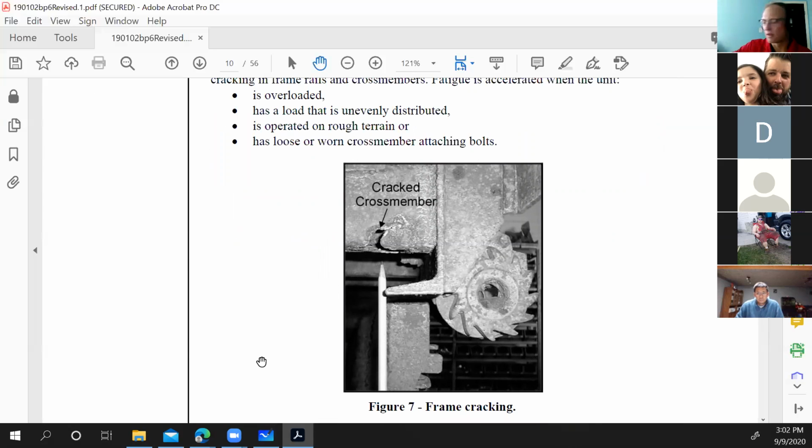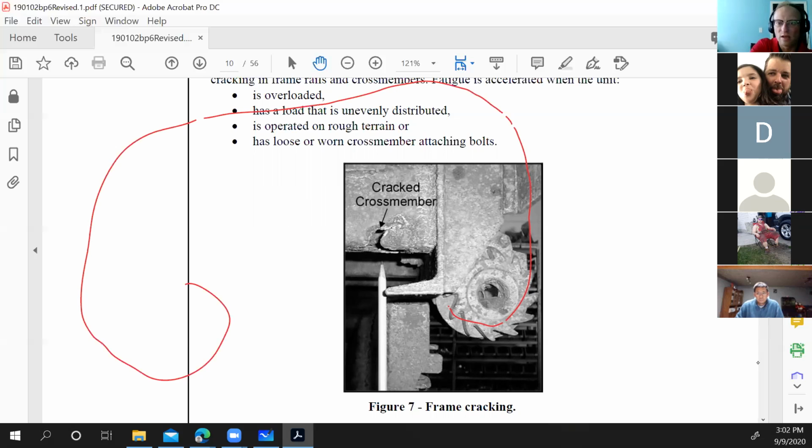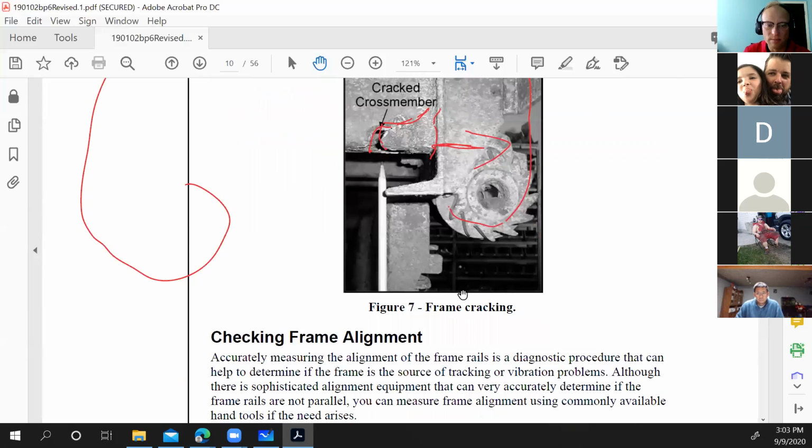The force of the ratchet is in here, and this wraps up around the load and then to another one on the opposite side. So it's pulling out this way quite hard. So if you start getting corrosion, this is where you could start getting those cracks. Okay, any of these load bearing areas, good to watch out for cracks.